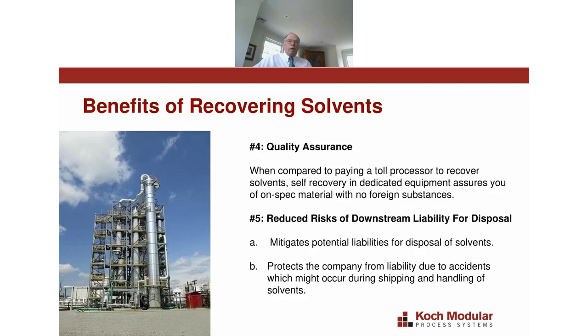Another reason why you ought to consider recovering solvents on site is that you can have better control over the quality of the recovered solvents. If you ship your solvents off-site to a toll processor, those toll processors use common equipment for many different separations, and you can risk having foreign substances get into your product.